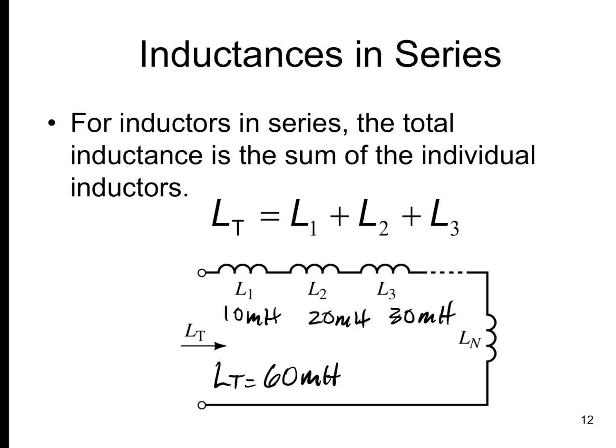Okay, this is part two of that presentation on inductors. So this is where we look at inductors in series and in parallel, and the combination of, to determine a total value of inductance, which, don't forget, is in the units henries. So L total is a total henry value or inductor value for these connections. Now you'll find these formulas on your formula sheet. So if you find the section on inductors on your formula sheet, you'll see that it says inductors in series. This is the way you come up with the total value. In parallel, and then of course you just need to know how to apply it to combinations.